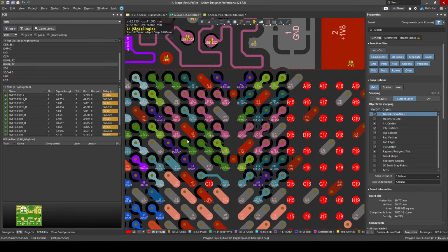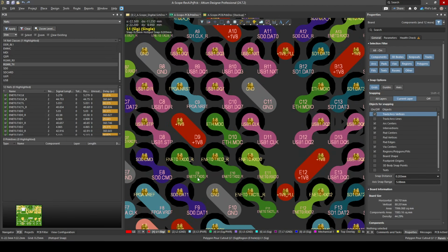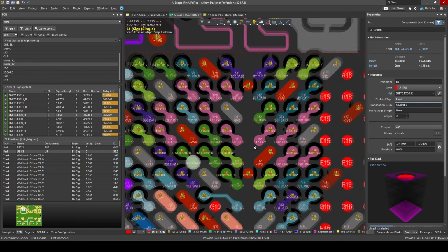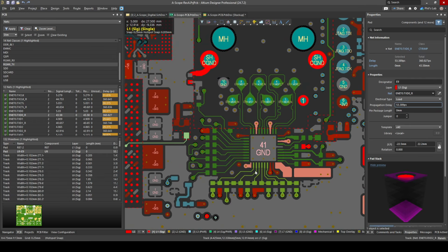If I click, for example, on my Mac on one of these pins, you can see every net also has its own propagation delay, which is due to the package delay of the particular component that I'm using. In this case, this is a Zynq System on Chip. I can extract the package delays from Vivado, but this depends on what processor you're using. So these need to be taken into account along with the actual trace delays themselves. So therefore, RGMII: controlled impedance, crosstalk, spacing, transfer vias, delay matching, and you're pretty much golden if you follow those rules.